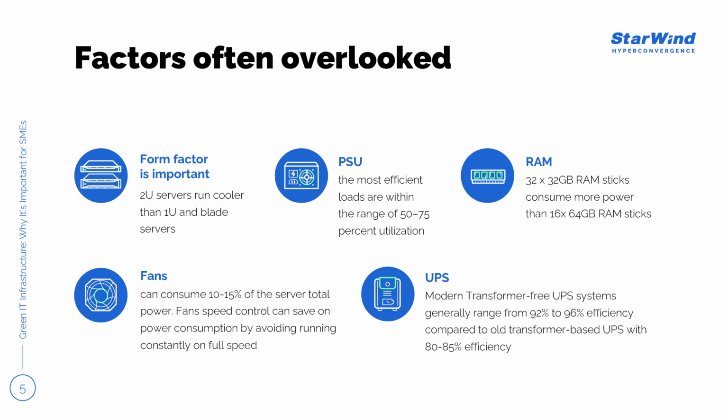Now, another option is very popular, and a lot of UPS vendors market this. That's what's called the energy saving mode or eco mode. This mode can boost the efficiency up to 99%. However, there is a small point that should be taken into account when using it. The UPS achieves this by actually operating as a line-interactive UPS.